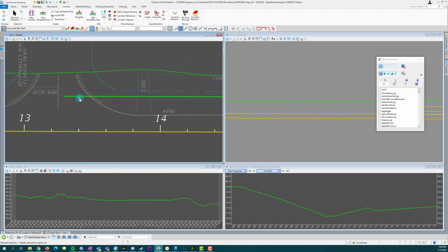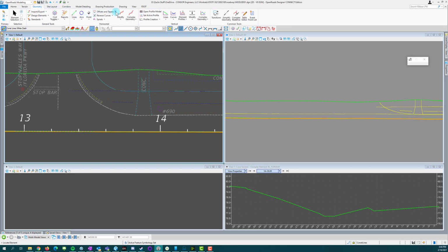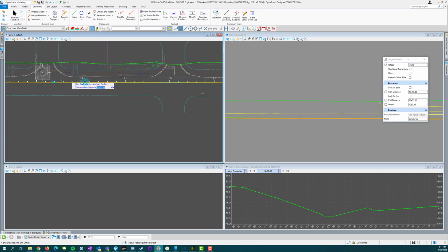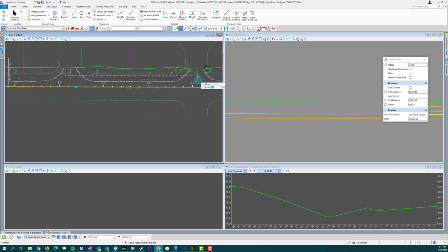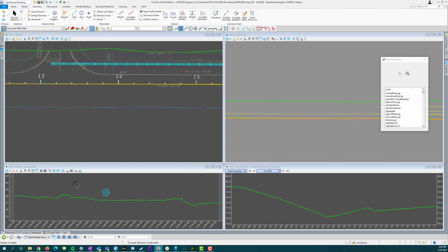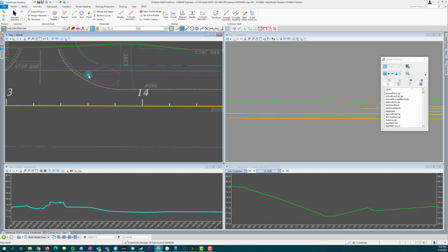I just realized something that I wanted to do here. Instead of having this line just sitting here, I want to go ahead and make a construction line out here. And that construction line is going to be my active, with the existing ground as the active profile to help me project things back to the center line. So we're going to single offset partial 26. We can just do this and this. So then that one is going to have my existing ground at my back sidewalk on it, like so.